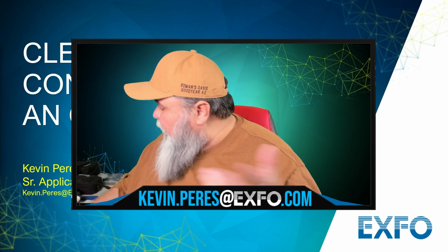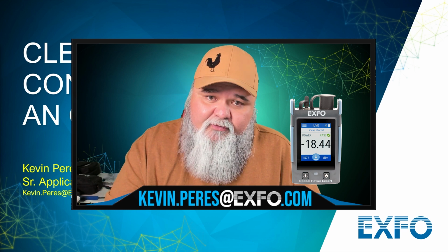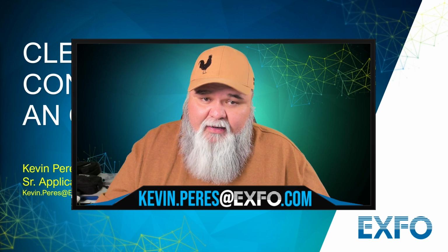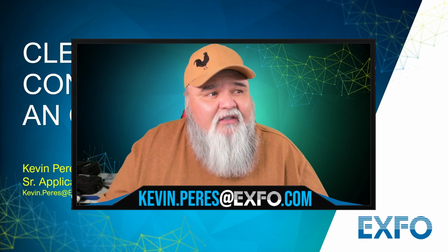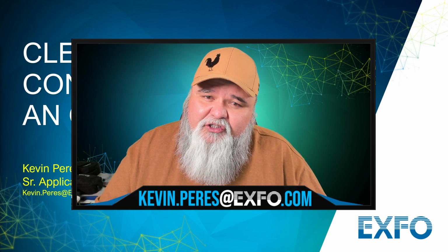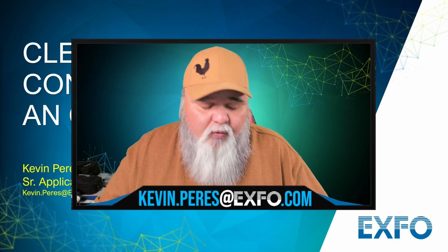So I would get out my standard power meter, which I have one here somewhere, and I would check light levels at the receiver, right? So I'd plug it in, and it would give me a power value in dBm. That's my light levels. And it would say, hey, I have neg 15 dBm of light. That's typically good light for most systems, and it should work. So I don't have a power issue. I probably have a noise issue, which is what reflection creates, especially in an amplified network.